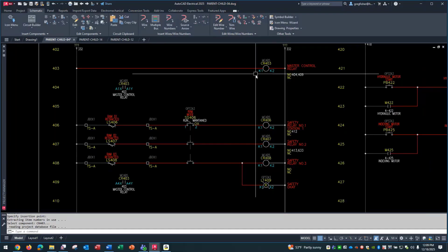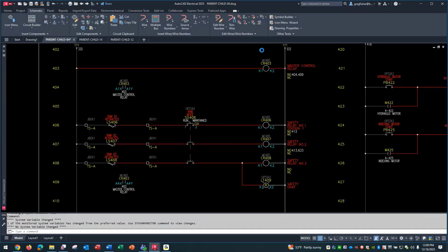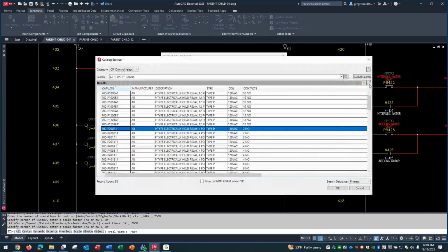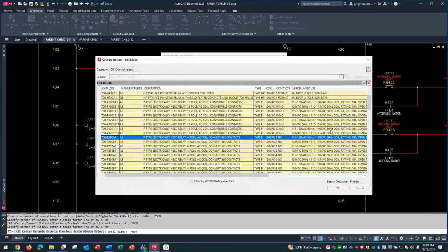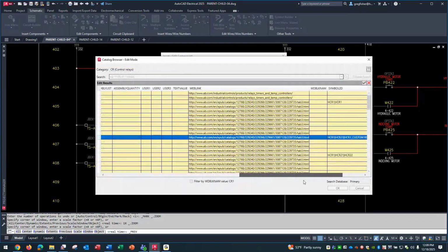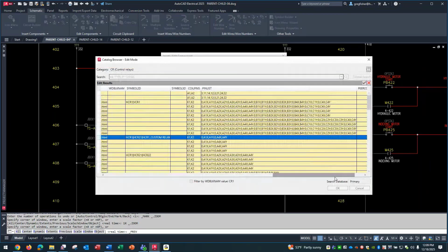And that's all done through the catalog number itself. So if I go to edit this, and this is where, when people first start using the software, and I go over this in class all the time, in the catalog number, to build that intelligence, to let it know that it's only, in this case, good for a two-contact relay, we have two columns in the catalog number, one for coil pins and one for pin list.